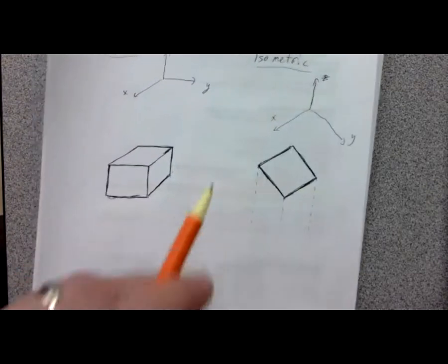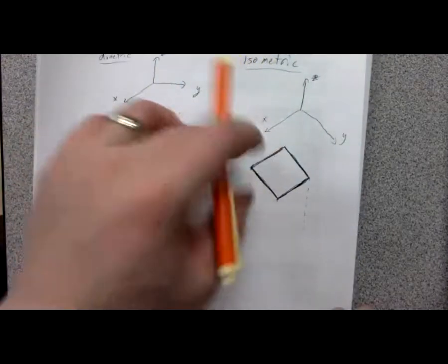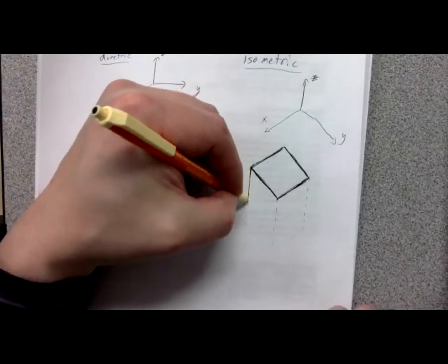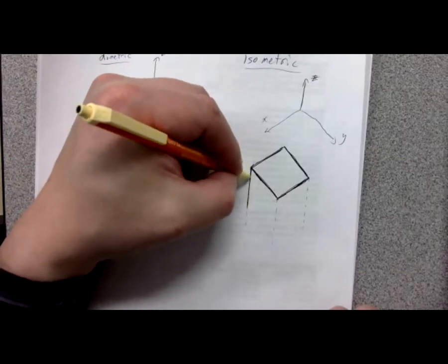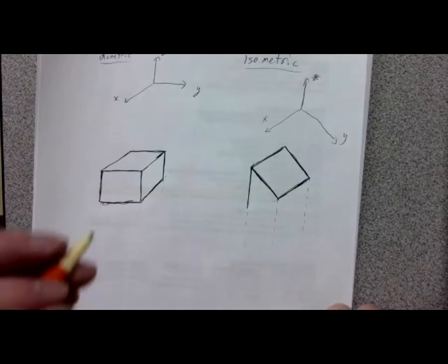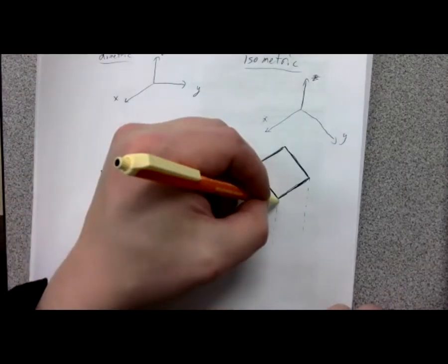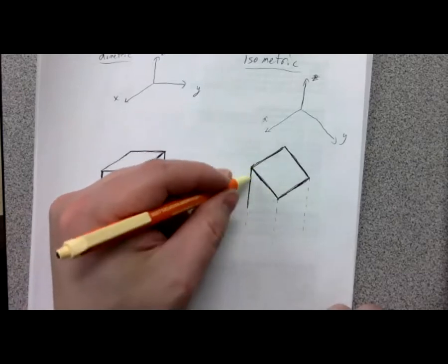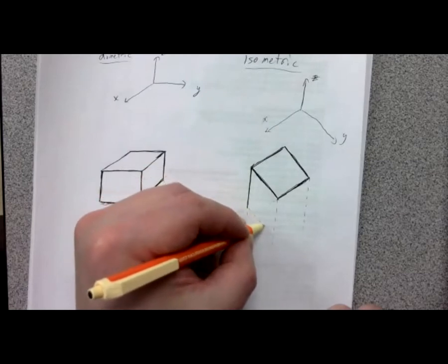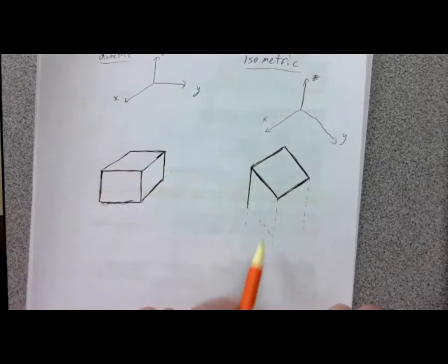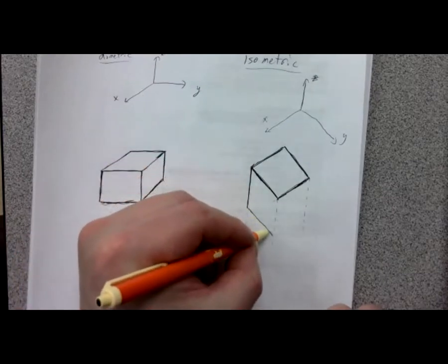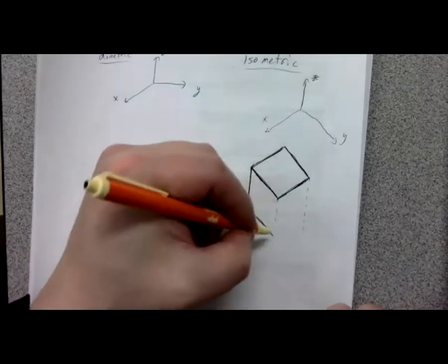And then, if you've got a ruler, we can roughly measure, but the lengths are not perfect because this is trying to represent 3 dimensions on a 2-dimensional medium. Not all the dimensions are exactly the same. But we can get the point across pretty easily. So we'll say it's this tall in the vertical direction. I'm going to dot a line parallel in the y direction to intersect this vertical here. That tells me where the endpoints are for this line, and that's going to define the endpoints for this line.